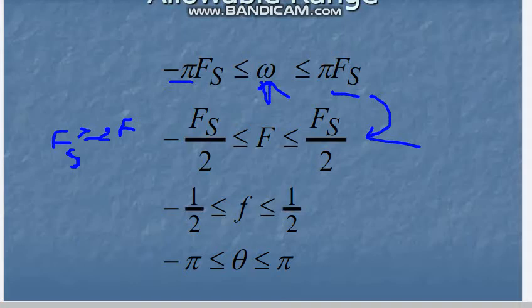To reconstruct the analog signal from the digital signal in the demodulation section, in the receiver section, you have to transmit the signal at twice its operating frequency, and that will be its sampling frequency. Okay, so it's pretty important while transmitting a signal.